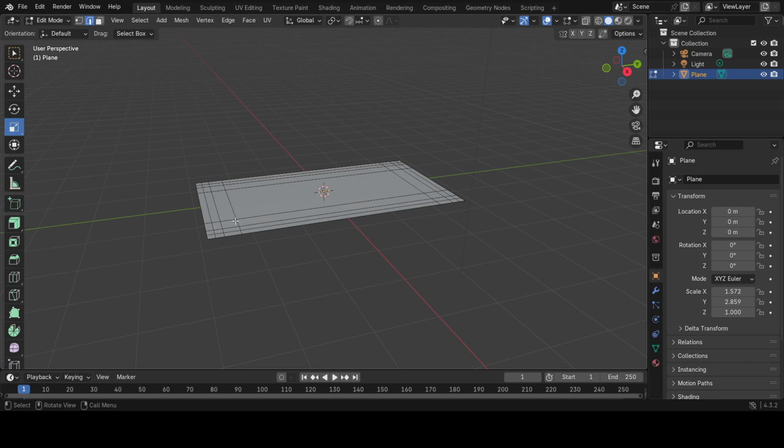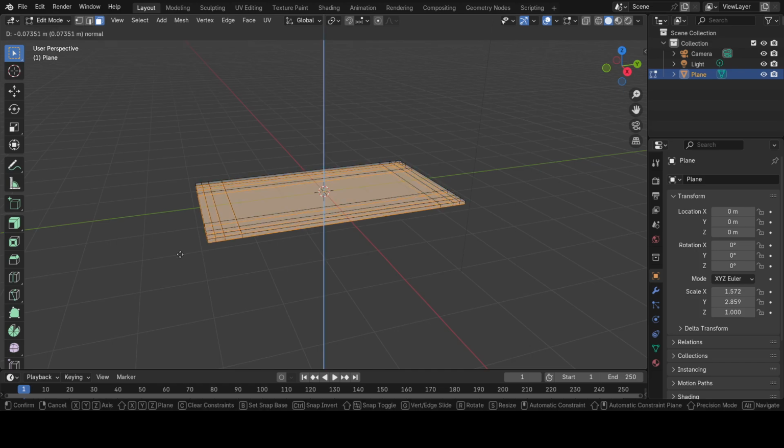Actually, in this case, we don't even have to do what I was going to do, but we'll continue here. Select all the polygons. I'm going to hit W so that I'm in the selection mode. But what I can do is hit E for extrude, and if I were to drag this down, you can see that this is turning this inside out.